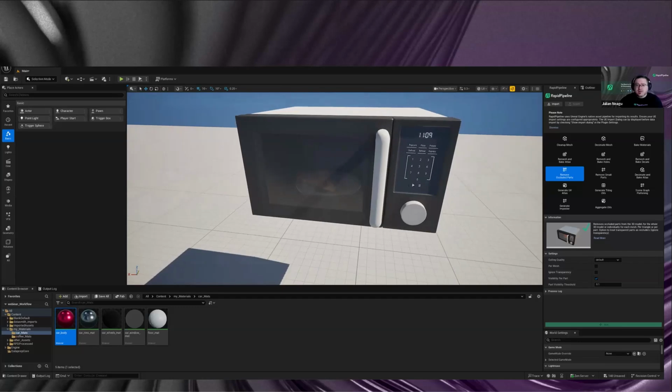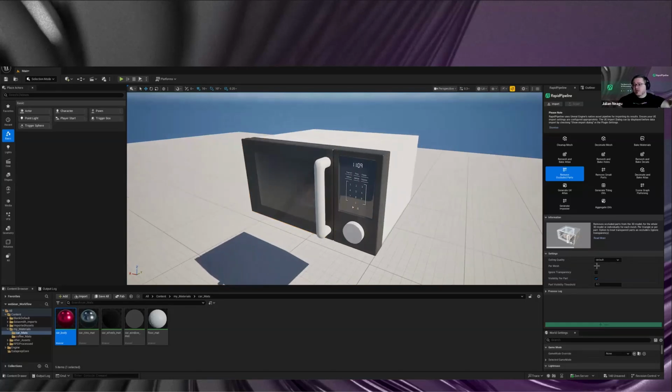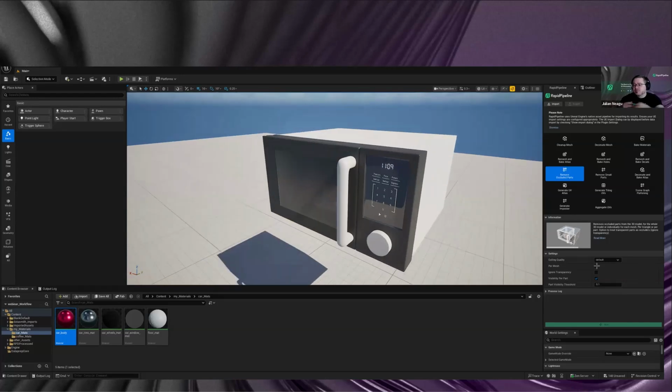And there's one more option, which is interesting for CAD, which is that we can do a per mesh culling as well. Meaning if you have a larger CAD assembly and each part has interior parts which might not be visible, but you want to have, for the configurator use case, for example, an exploded view where you actually move parts out of each other, have an animation or something. And then it might reveal interior parts which are actually important to reveal.